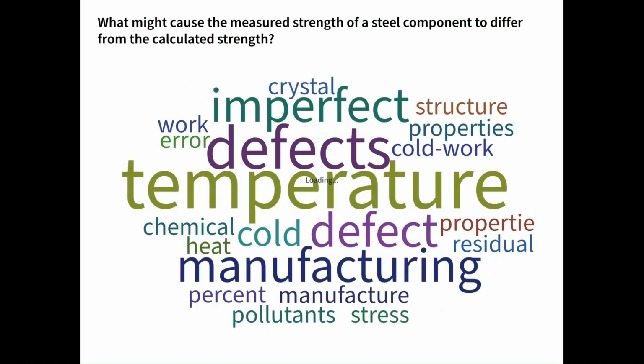The stress or the strength of the steel might differ. I'm telling this mill manufacturer I need 350W steel, which has to have a strength of 350 MPa. But if I take their steel and cut it up into little coupons and test them all, I'm going to get 340, 360, 355, 380. The strength depends on lots of things that we can control relatively well, but it can't be perfect. We can never have exactly 350 MPa. We can never have exactly half an inch.